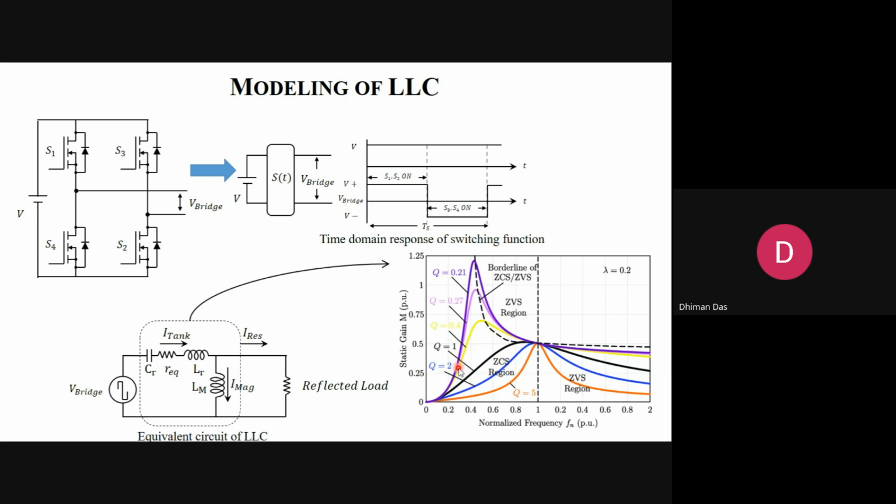You can achieve ZCS, but with ZCS you cannot gain a reduction in switching loss. Your ZCS does not help with anything. It can help in the EMI performance, but you cannot gain other than the EMI behavior. You cannot gain a reduction in switching loss.